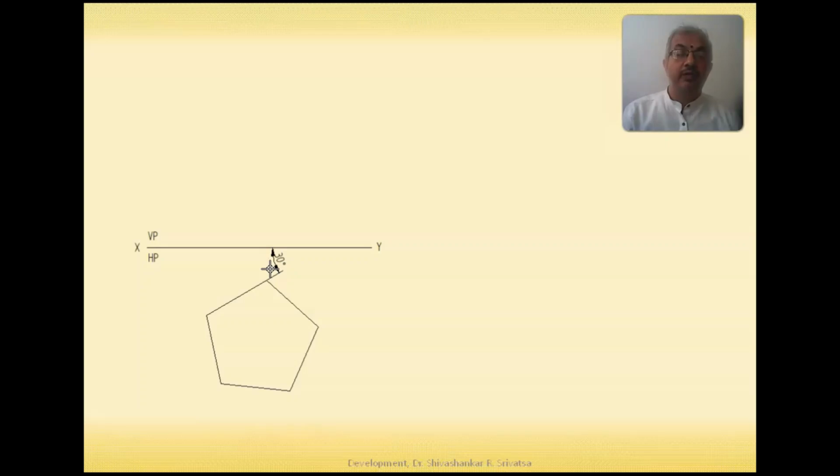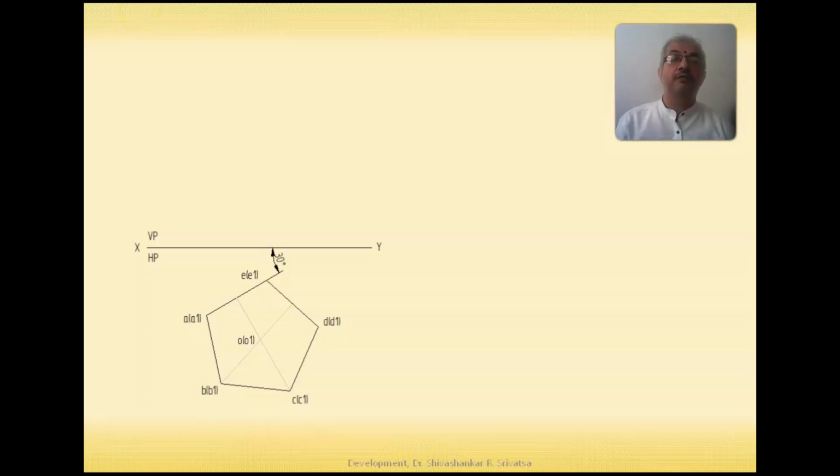So we'll do the naming of these endpoints in this fashion for a prism, and I'll try to identify the location of the axis. I'll draw any two medians to find out the centroid. Once we get these points in the top view, we shall create the front view.